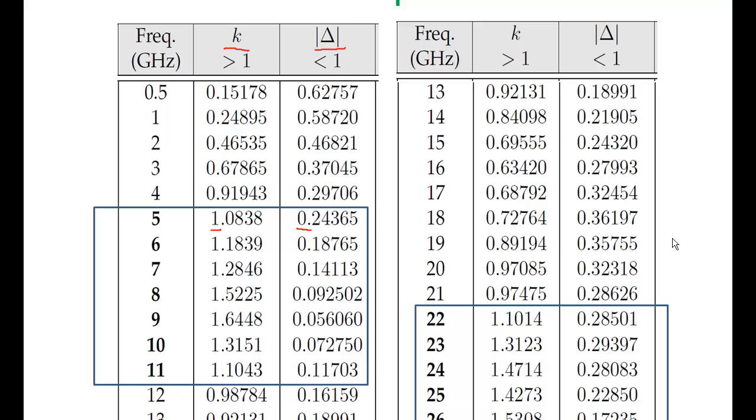At these high frequencies our field effect transistor has lots of capacitive parasitics internally, and those capacitive parasitics are shorting out our circuit. So we usually find with an active device that it's going to be stable at fairly high frequencies, but we're probably not going to get useful gain out of this device at those high frequencies.